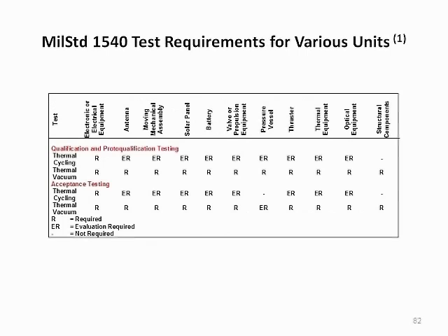MIL Standard 1540 contains explicit guidance on the applicability of thermal testing requirements to different kinds of hardware. It requires both thermal vacuum and thermal cycling for electronics, and at least thermal vacuum for most other kinds of hardware. Since the main purpose of thermal cycle testing is to stress electrical connections, its applicability to testing of components containing few or no electrical components requires evaluation on a case-by-case basis.